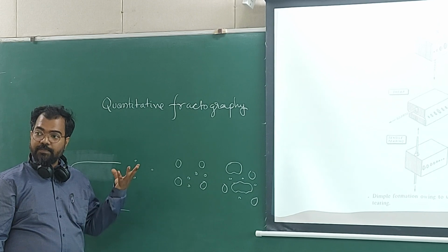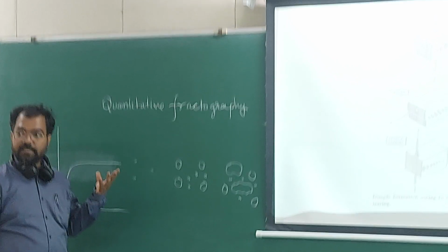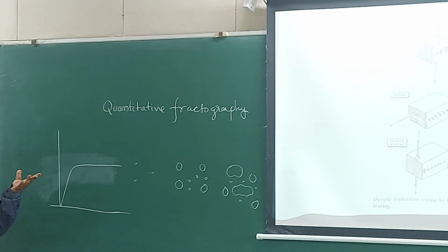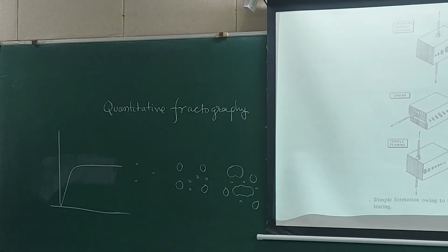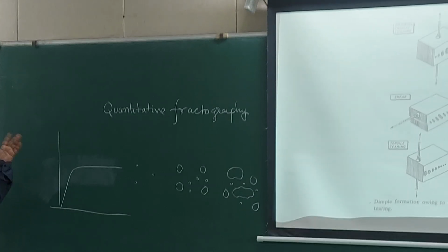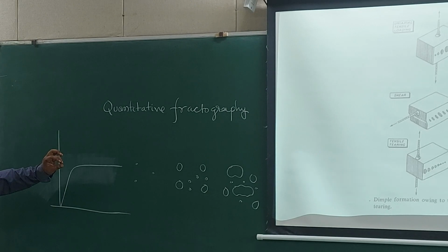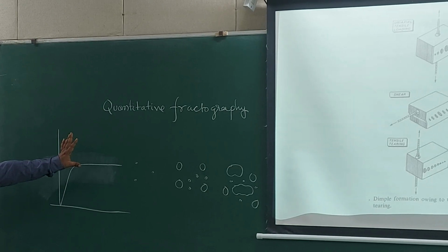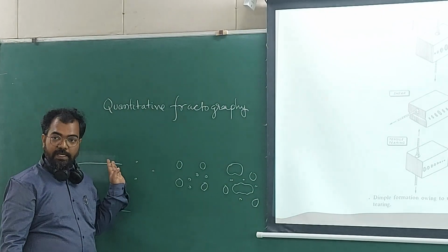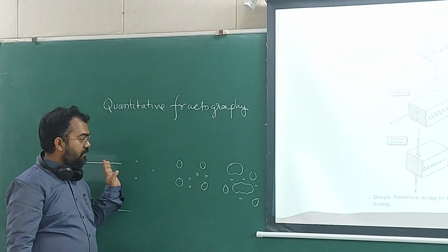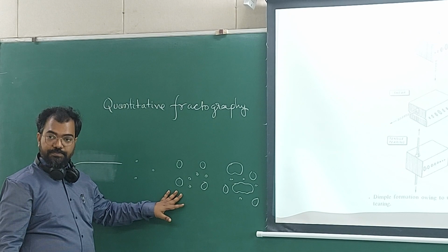So how the design of the material is inside, and when I say design, not mechanical design, design meaning how the microstructure is. So how many precipitates you have and secondary phases you have, on those it depends where and how many nucleation will happen. Okay, so nucleation site is not controlled by material deformation property, but growth is.